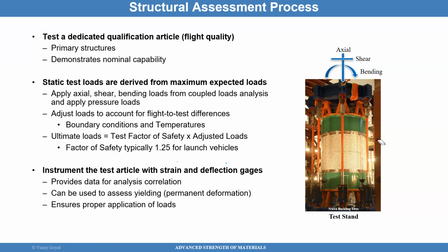While on the ground the wheels are touching the ground, but you have to replicate the flight loads. And the only way to do that is to use analysis to show that the test conditions are worse than flight. So you're using analysis to show that whatever you tested is worse than flight. And if you pass the test, then you're good to go. But the only way to do that comparison is analysis.